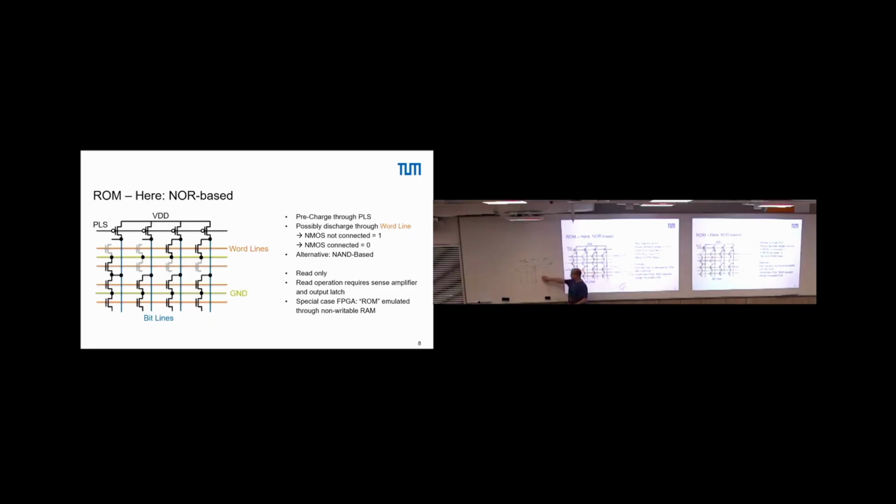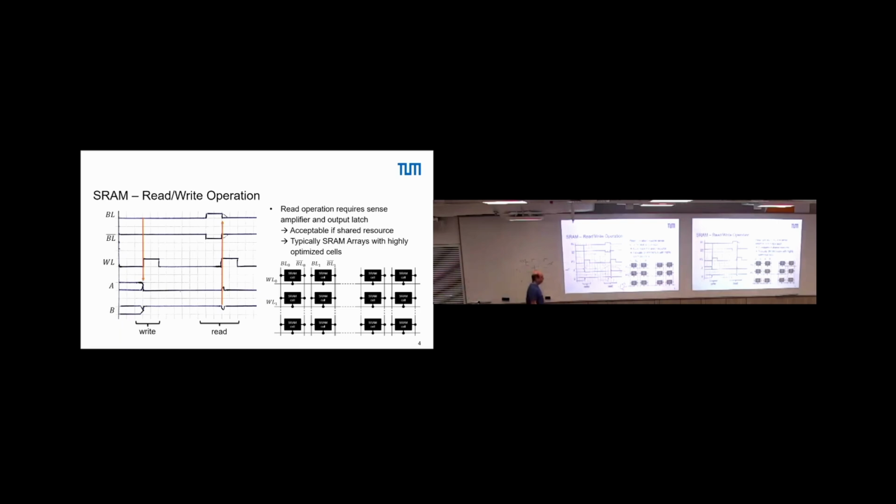How is the word line controlled, actually? You have a control logic on top. So your overall memory looks like this. Instead of the SRAM cells here, now we have only one bit line and only one transistor to discharge, but overall it looks pretty much the same.